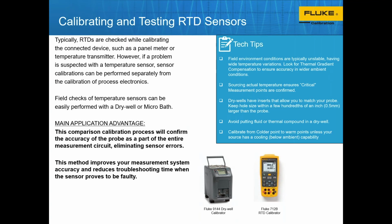But what we recommend is you start from your cold temperature and go to your hot temperature. The reason is that we have much better control at being able to bring that temperature up rather than just blowing a fan on everything and attempting to cool it back down using ambient air. So again, doing a calibration using a dry well, if you had 3 points of calibration, we would recommend you start at the colder 0% point, go to your 50% point, and then go to your 100% point.